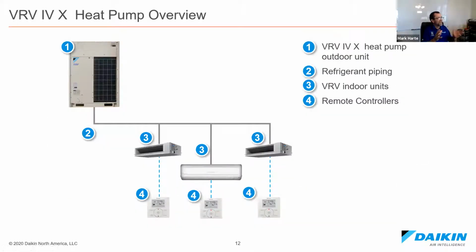Now, a typical layout of a heat pump system, you have the outdoor unit, number 1. Then you'll have your indoor units, numbers 2 and 3. Now, the refrigerant piping, we'll talk about the circuits you see there where they split off. We're going to talk about Refnet fittings in a little bit, refrigerant network devices. They're basically refrigerant wyes that split so we can pipe all these fan coils off of one outdoor unit. We call them outdoor units, not condensers, because they can be an evaporator too. 1, 2, 3 outdoor units. We can twin 3 together depending on the capacity we need.